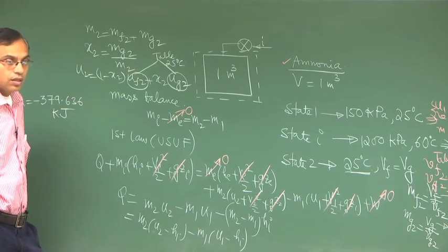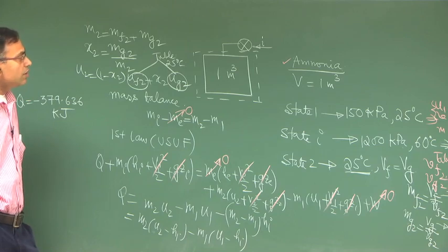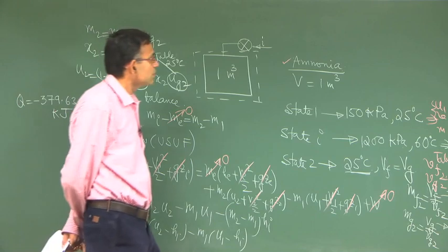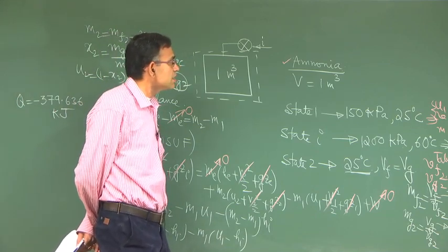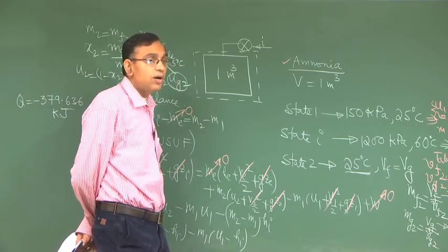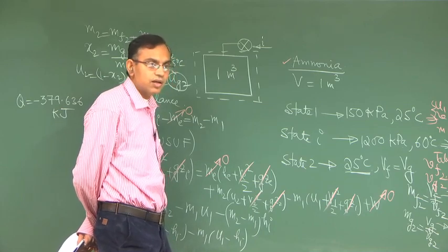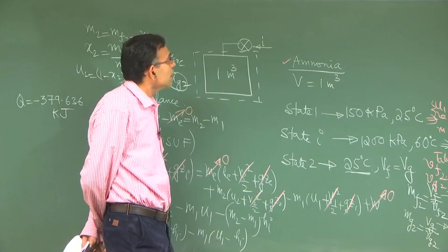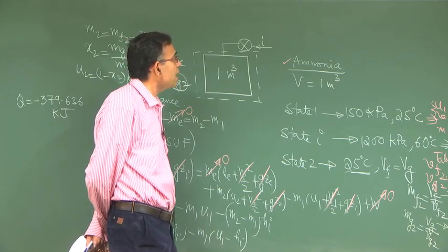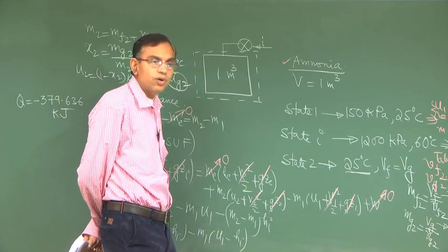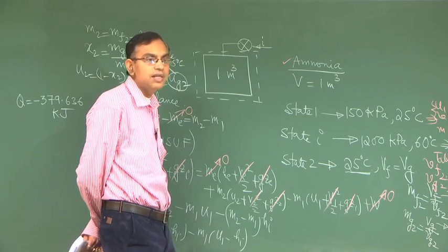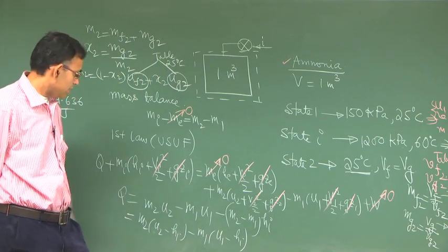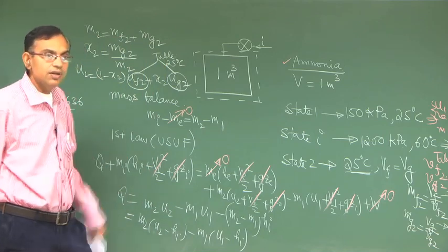Okay. So, again you see that there is a heat transfer which is required from the control volume to the surrounding, because you are energizing the fluid more by supplying the flow energy or flow work. So, that energy somehow has to be dissipated through heat transfer to the surrounding. That is why this is a negative heat transfer.